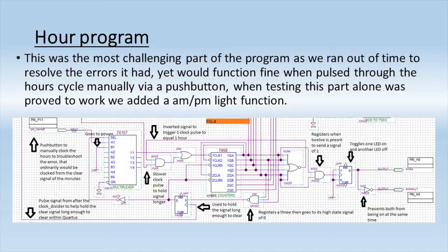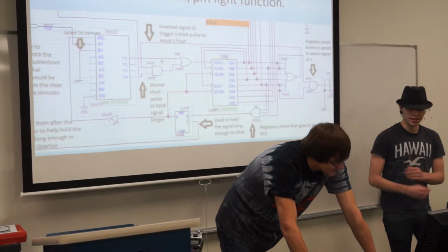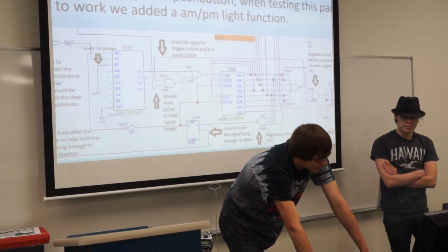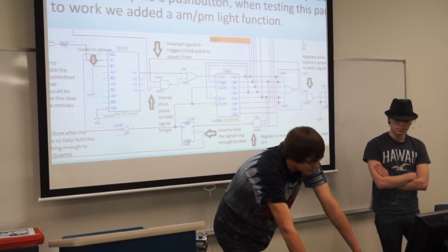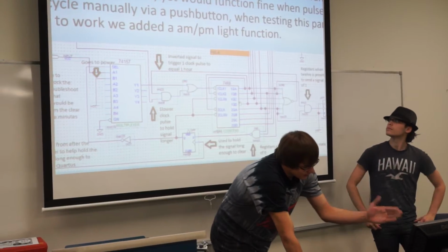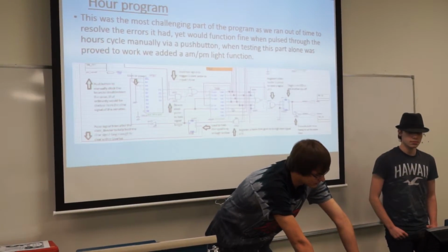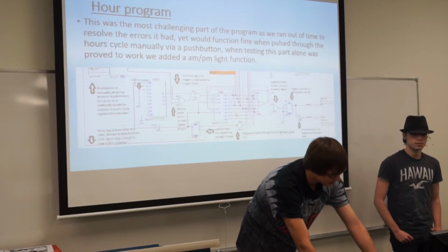Now the hours are a bit funny. Not like haha funny. Getting it to function. This is still the same counter we've been using for the minutes and seconds. We got some more stuff back here, but this would also count to 99. Can't have that, but we don't want it to count to 60 this time because you only want your hours to display up to 12. So this at most would display a 2, and this at most would display a 1, being the leftmost 7-segment driver.